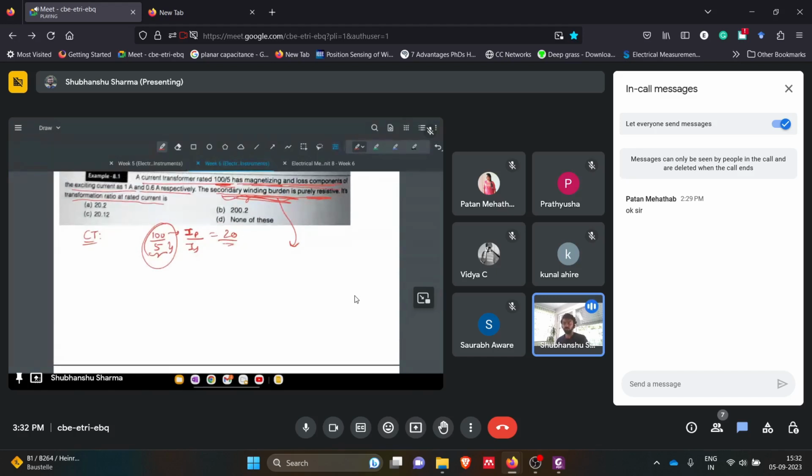Just recall, you have been taught the equivalent circuit of this transformer. We have the winding resistance, the magnetizing reactance Xm, and I naught here. We have the coil winding, the secondary winding, and then a load. This is the secondary side and the primary side, and this is the input, the line voltage, V1 or VP. And this is EP, and this is ES.